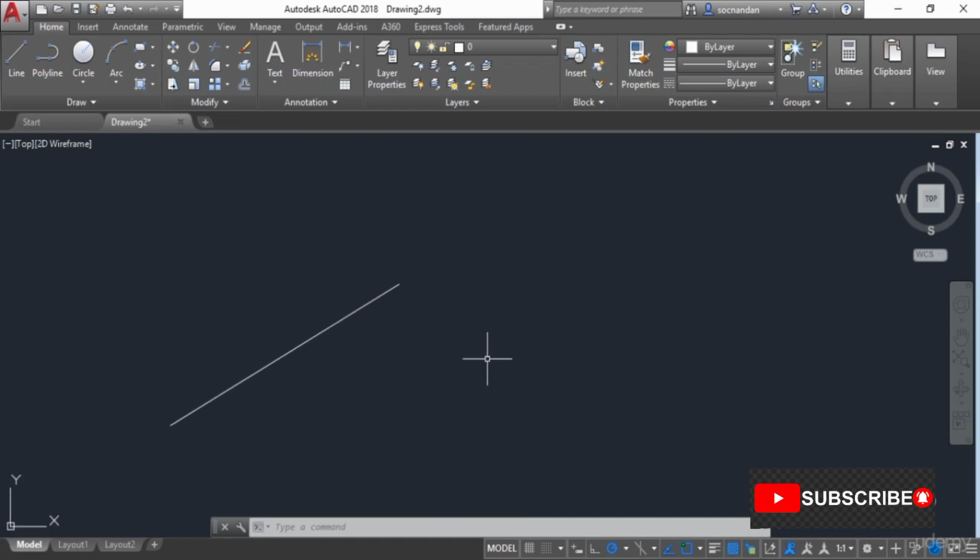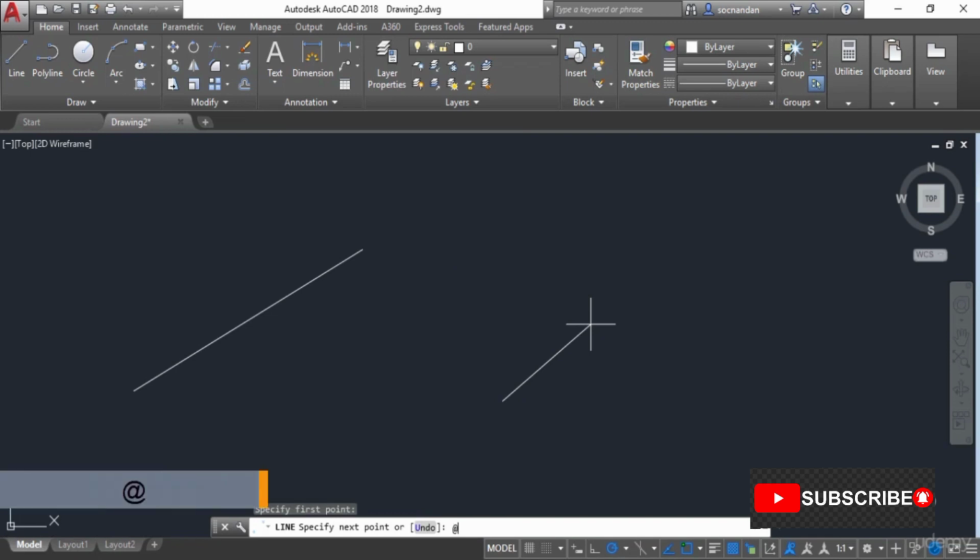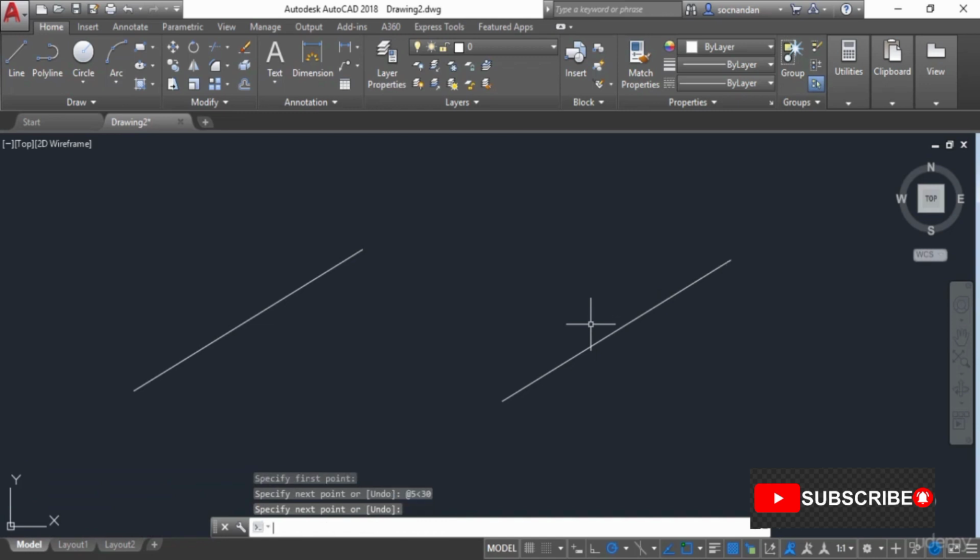Now there are also some other ways of making the same line. So I'll select the line tool again, click at any point here, and now if you want to make this line directly using a single command, then type @. As you know, we have used the @ symbol in the previous lesson also, so that will add a relative coordinate system. Now enter the length, which is 5, and now type the angle sign and enter 30. So this will be the angle. The normal syntax of this command is @ length of line, angle sign, and then angle value. Now press enter and press enter again, and we have this line directly using a single command.